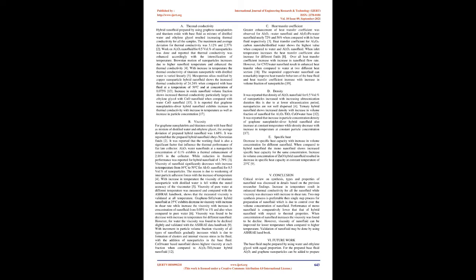Mesoporous silica modified by copper nanoparticle hybrid nanofluid shows an increased thermal conductivity of 24.24% when compared with base fluid at a temperature of 50 and at a concentration of 0.075%. 13. Increase in oxide nanofluid volume fraction shows increased thermal conductivity, particularly larger in ethylene glycol with CuO nanofluid when compared with water CuO nanofluid. 15. It is reported that graphene nanoplatelet silver hybrid nanofluid exhibits increase in thermal conductivity with increase in temperature as well as increase in particle concentration.